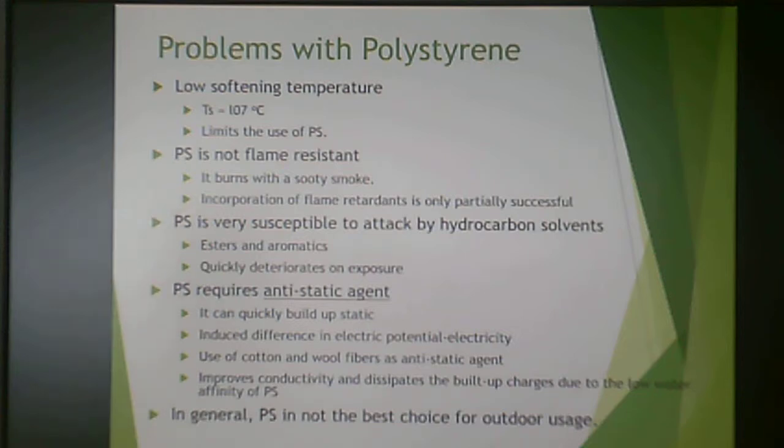It is not flame resistant, and it burns with a sooty smoke. And when you incorporate flame retardants into polystyrene, it's only partially effective, so it's not good for anything that may be in a situation where it may be exposed to flame. It is very susceptible to hydrocarbon solvents, and it quickly deteriorates on exposure.